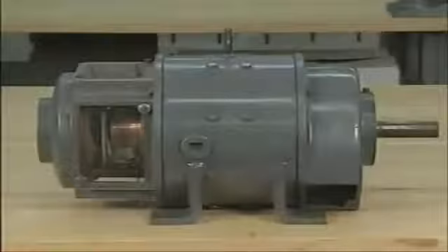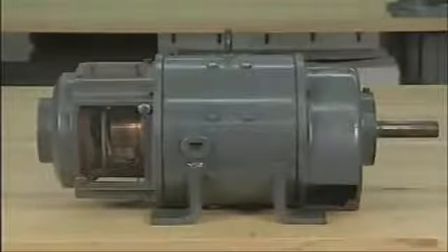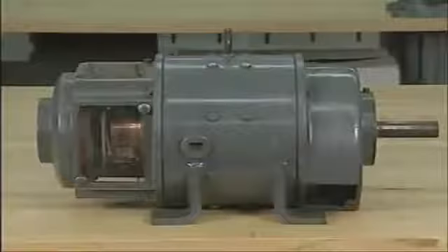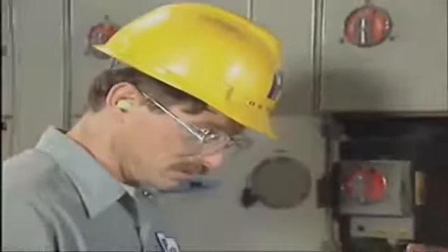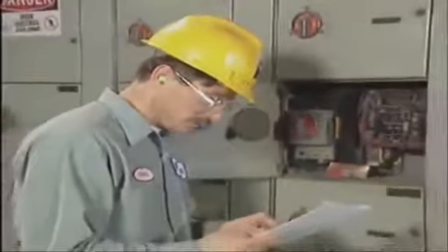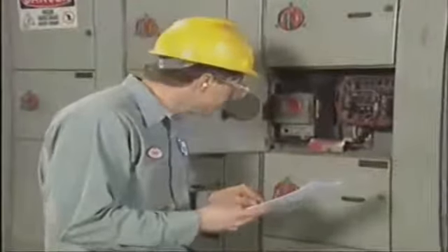The external appearance of all DC motors is very similar, but there are several ways to distinguish one type of motor from another. For example, this is a nameplate from a typical DC motor. The entry in the block labeled wound identifies the type of motor it is. In this example, the block contains the letters CPD, which means that the motor is a compound motor. You can also determine what type a motor is by referring to a schematic diagram in the manufacturer's manual.